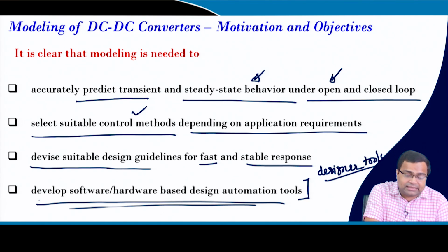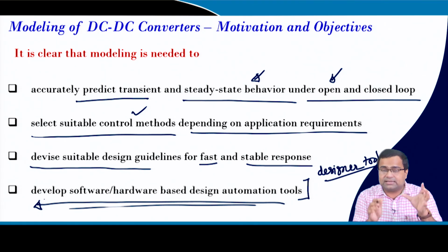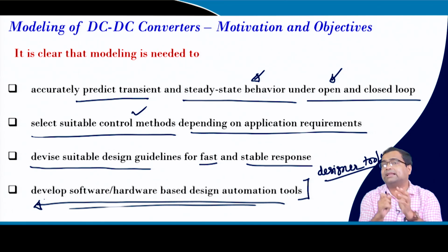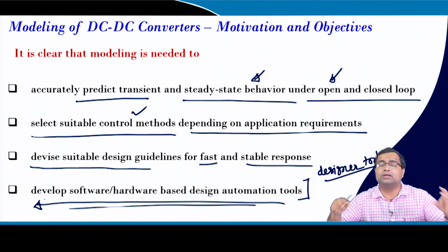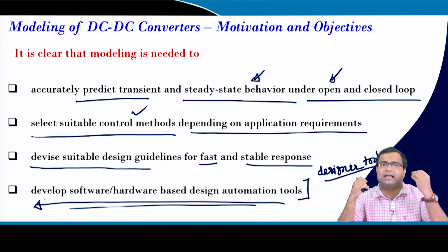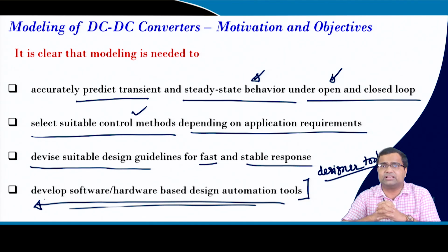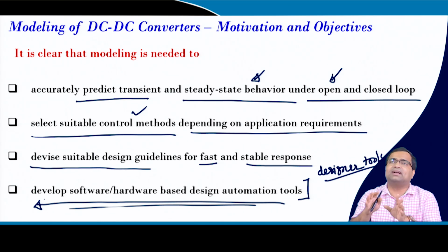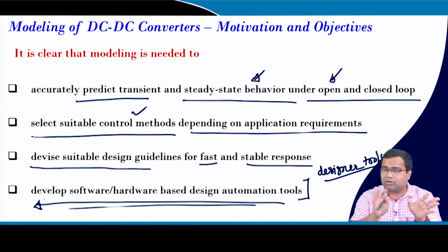In fact, in this course, whenever we go for design, I will demonstrate some MATLAB .m file, where if you specify some gain margin, phase margin, or even some phase margin and control bandwidth, then it will give us the compensator gain for a given inductor, capacitor, input voltage, and output voltage. Then you can obtain the compensator, plug it in, and match the response of the model as well as the switch simulation.